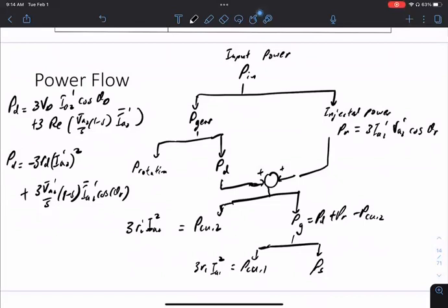So you need to solve a set of equations to figure out the right one. For each S, each amount of power the grid wants to get, there's some VA2 prime and theta R for each particular S and each particular power I want from the wind turbine. And in real time, this one subtract this one is normally kept constant. S changes all the time. So for changing S, this part of the equation changes, and your job is to change this number to still track this target. Does that make sense? Yeah, go ahead.